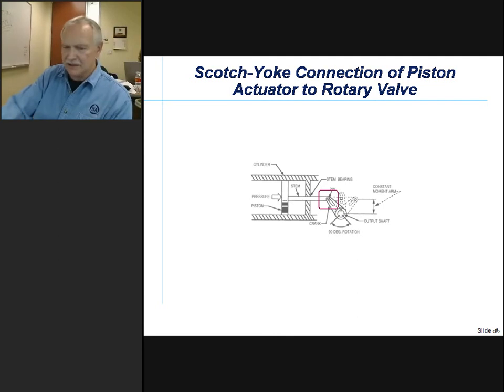And then if you look at the fact that the tight sealing, tight shutoff, very low leakage associated with these piping valves creates excessive seal friction, we end up with additional problems in terms of stick slip for these piping valves that are used as rotary valves. And this became very popular in the 1980s and 1990s because it looked like a cheap solution.